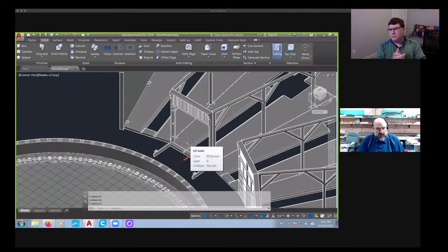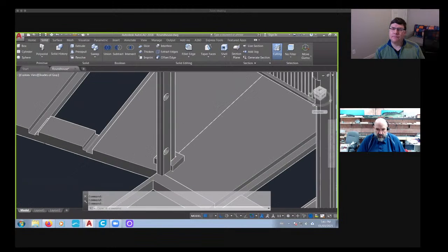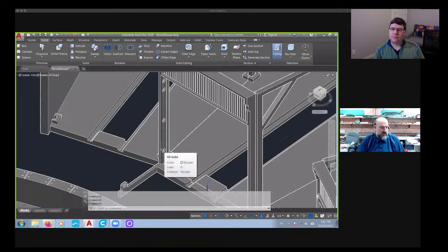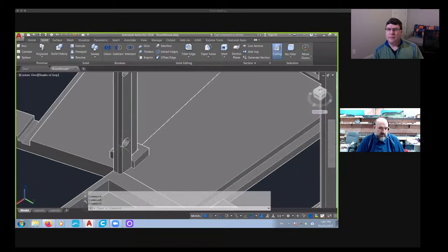It depends on the part. For example, my wings for the plows, I've got to scale them at 101% to have the magnets match up to the plow front. So it's more trial and error. It also could do with the calibration with the FDM printer versus the SLA printer. It might be a little bit different.